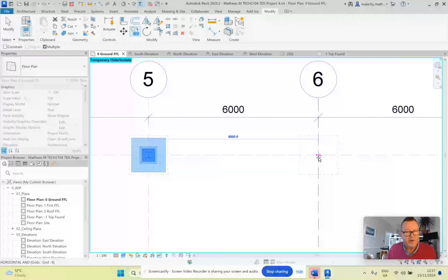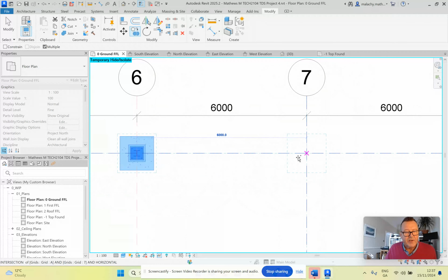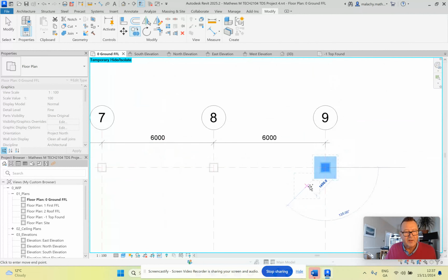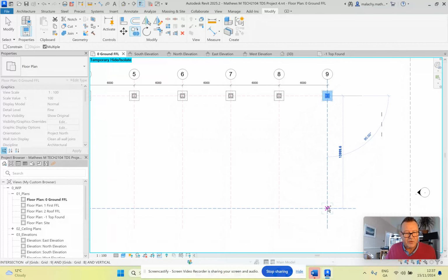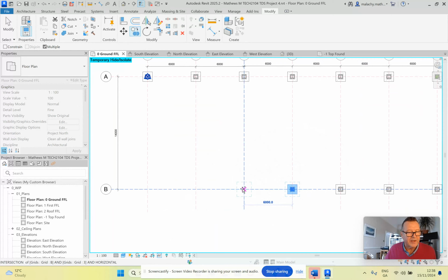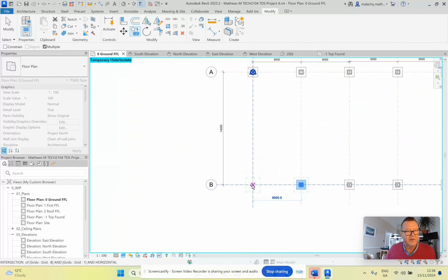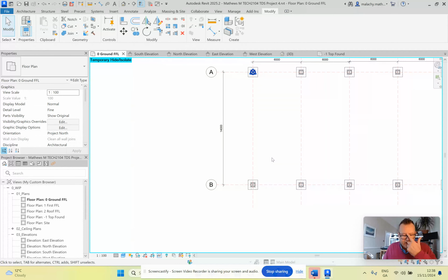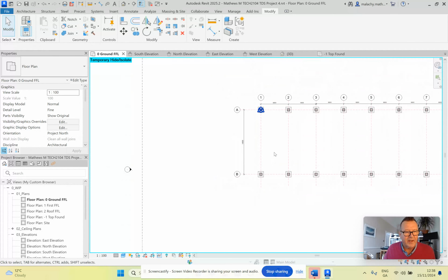So there's a little bit of working out to be done in terms of the height, the location height that you're going to put your columns into, and my main concern is the thermal break, particularly in a building like this that is an office where we're going to have an enclosed space, and with a little bit of forethought you can avoid those thermal breaks by doing that.